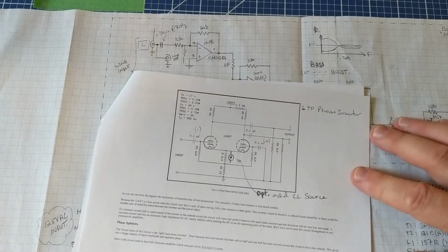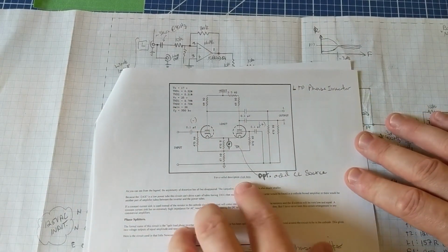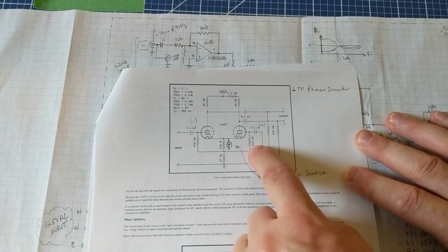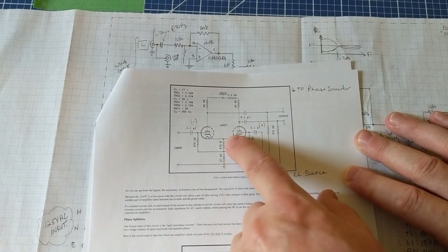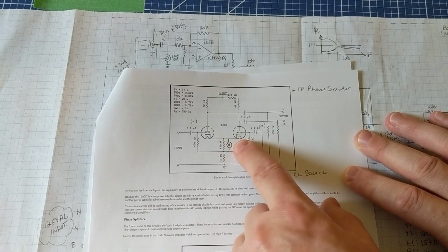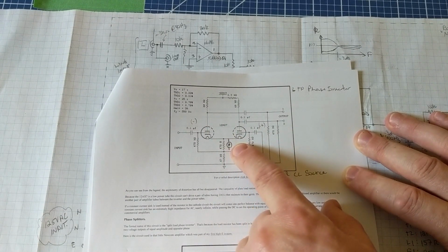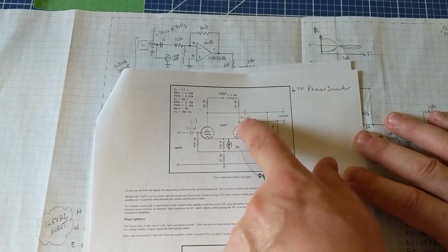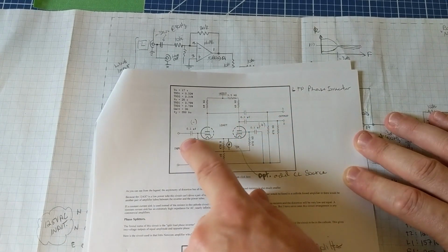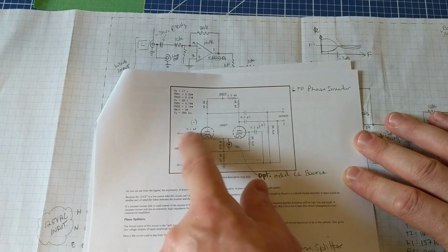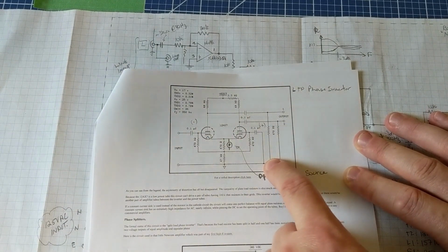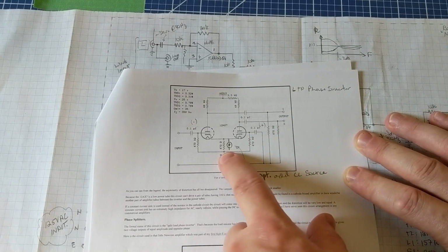This is another shot of the long-tailed pair, more traditionally drawn in the way that a more modern design using transistors would be drawn. You can see here in the vertical orientation the common tail, with, in this case, a constant current source I drew in to replace the 470 ohm resistor, and then on the plate sides we pull off the output signals. So this side here would be a signal coming in. The other side is essentially clamped to ground in terms of the AC, and in terms of the DC it's biased to this point in the tail equally with this one here.